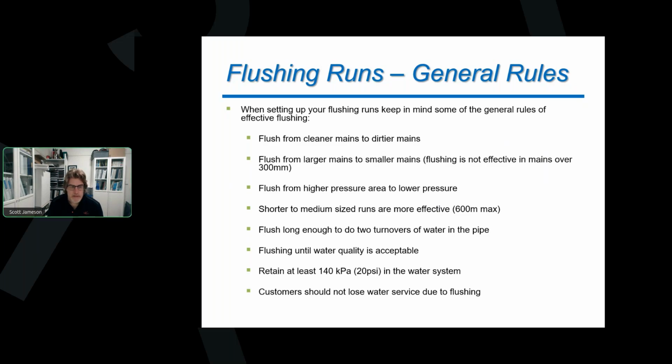Now, the last couple of ones there, these are things that we're maybe going to have to do some calculations for. We're going to make sure that we time our flushes so that we can do 2 turnovers of water in the pipe. And this is, again, an AWWA recommendation. This is how to do effective flushing. And we'll show that calculation coming up here.